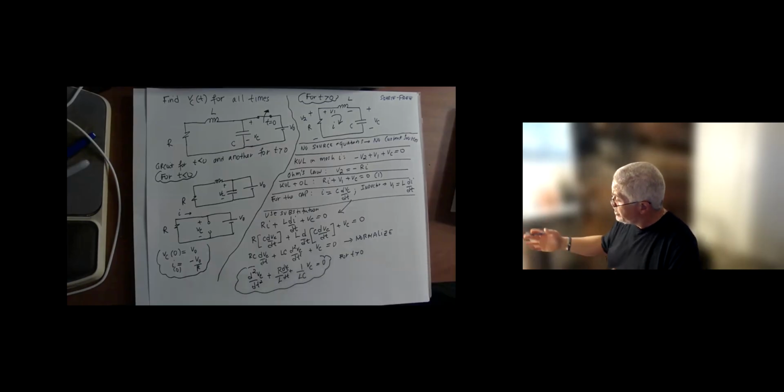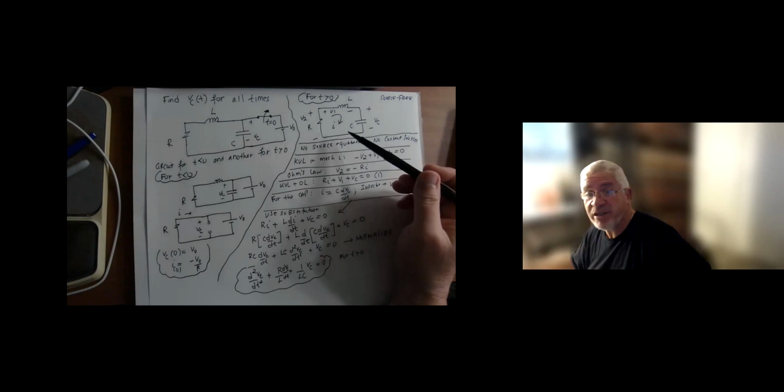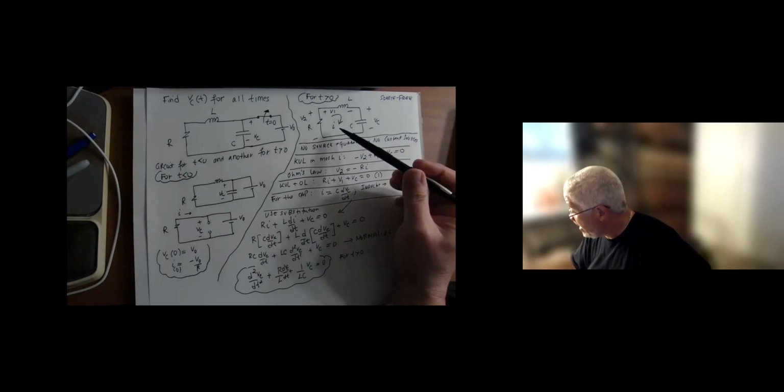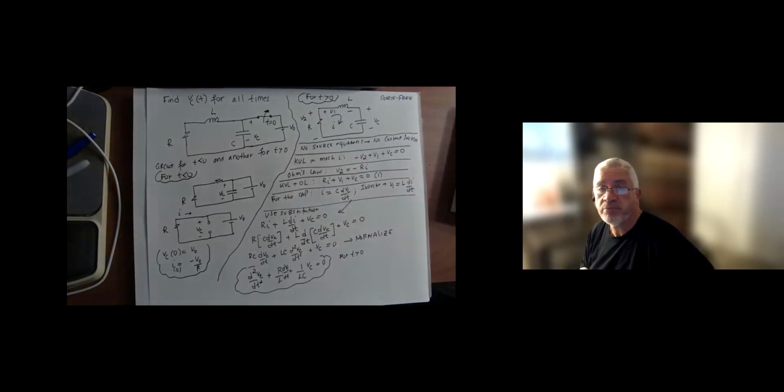Okay. So the first thing I do, I prepare the circuit here in a typical mesh fashion. I identify my finite meshes. I put mesh currents in each mesh, each finite mesh. It's only one mesh. I get that. And then I put voltages on all my passive elements that don't have voltages. So the capacitor already had VC. I don't add another one. And I put a voltage plus and minus and label on the inductor and the resistor.